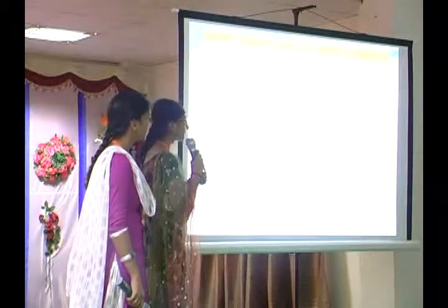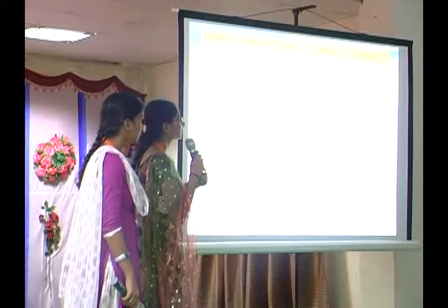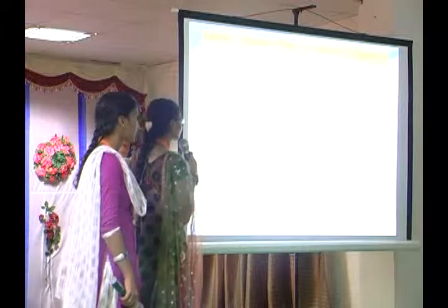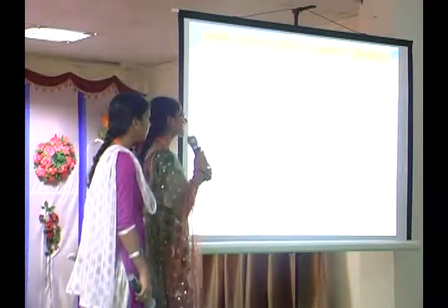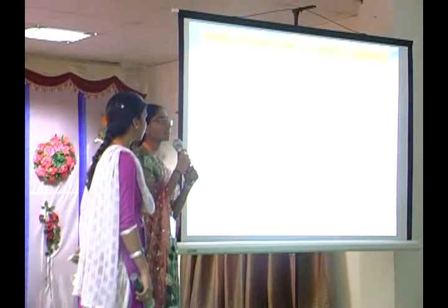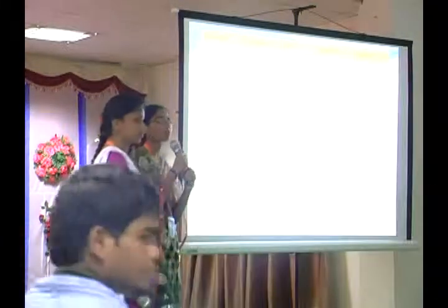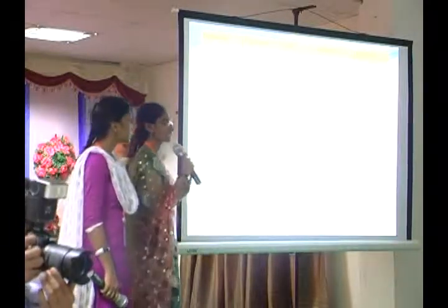Infrared has potential for surface contaminant effects. Resistive is unaffected. Compared with all other technologies, the sensor substrate is made of indium tin oxide only, because it has the property of both electrical conductor and resistance.